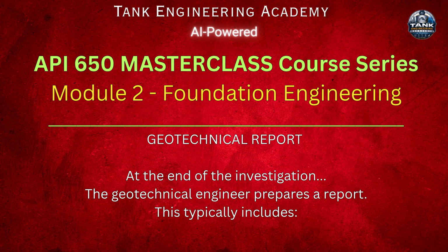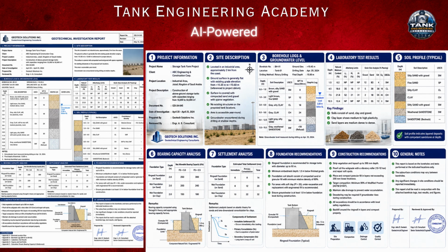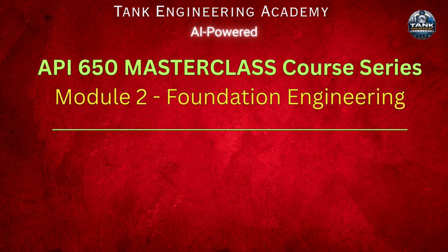Geotechnical report. At the end of the investigation, the geotechnical engineer prepares a report. This typically includes project information, site description, borehole logs, groundwater level, laboratory results, soil profile, bearing capacity, settlement analysis, foundation recommendations, construction recommendations. This report becomes one of the most important design documents for the project.